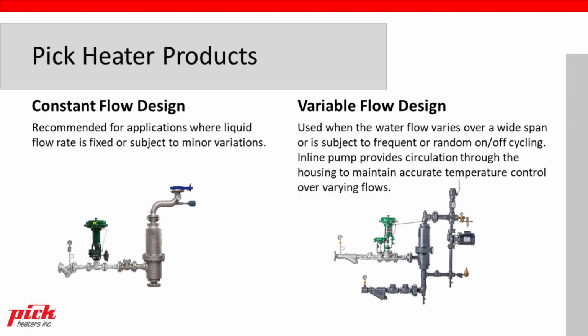So the PIC heater products that are on the market are, starting with our constant flow design, that's recommended for applications where the liquid flow is typically fixed or subjected to minor variations, like maybe a 2 to 1 turn down or even 3 to 1 turn down. So water flows to a tank or to a process, but there's very little change in flow rate. So this constant flow design is very well suited for that application.